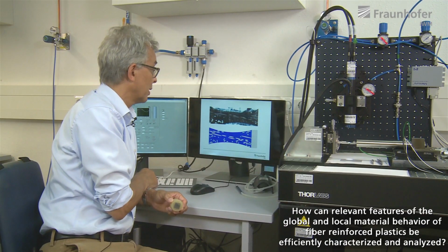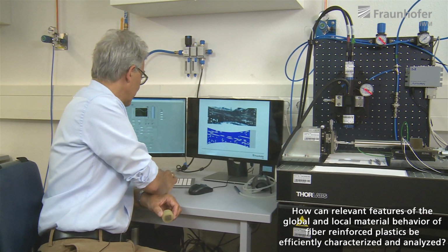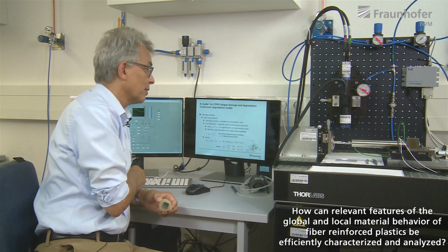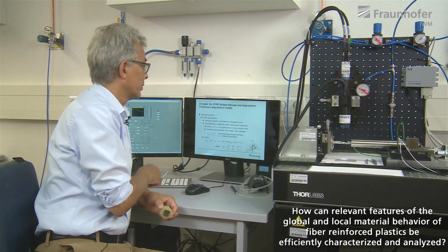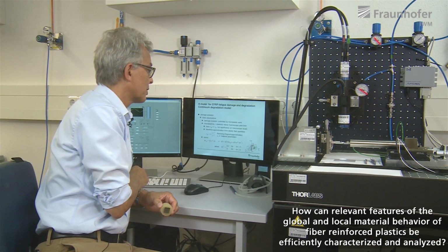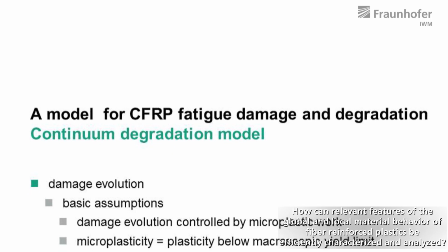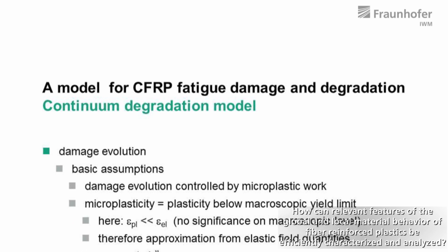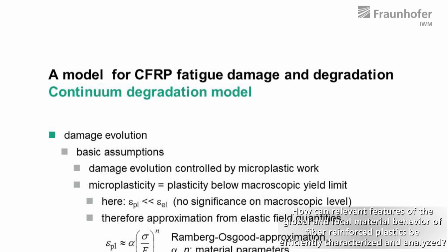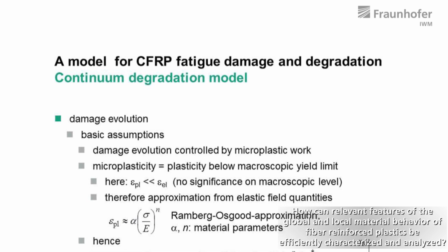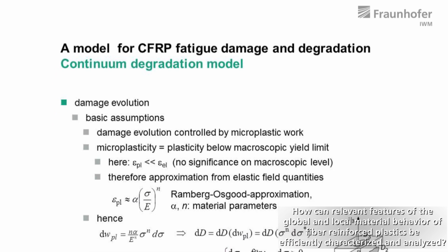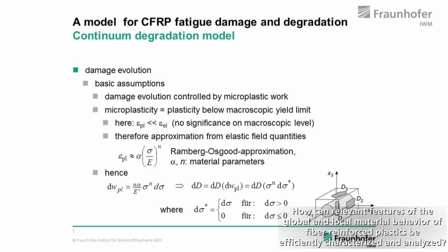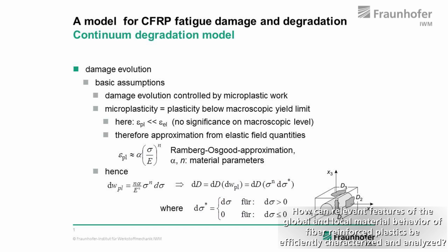But as we say, behind every colorful picture there's got to be a powerful material model, and this slide shows some overall rough details about what we put into the material model. And you see that we use representative volume elements and accumulate damage in the volume elements to be able to describe the deformation behavior of the whole specimen.